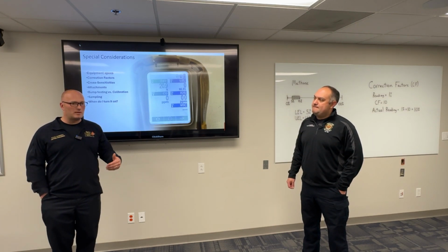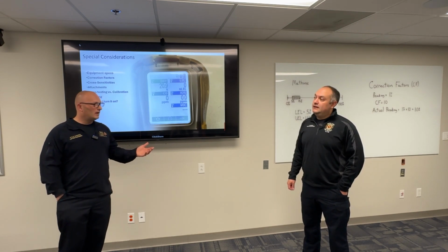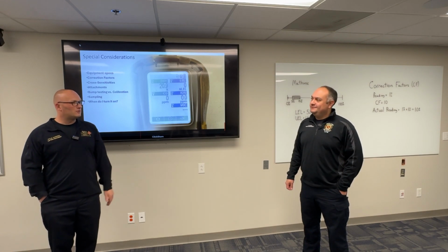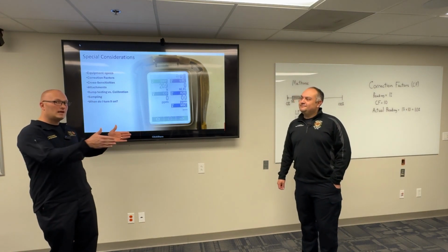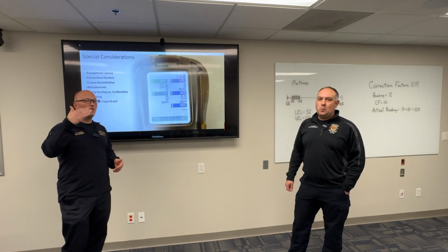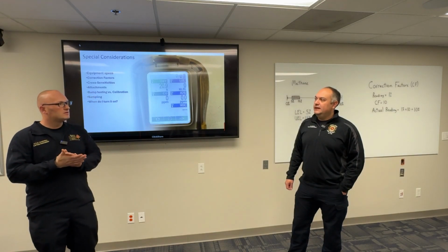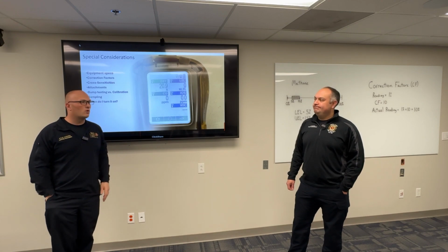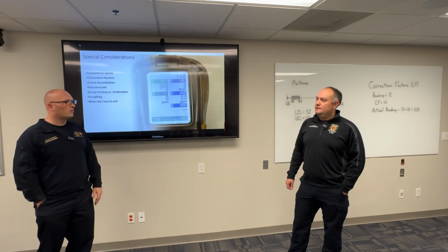I've had those calls where people have been baking all day long. It's around Christmas time, holidays right now. And 5 or 6 hours later is when their CO alarm's going off. And you try to figure out, well, I've been baking pies all day long. Okay, well, that's going to help me guide down to, hey, it might be something with your oven, and it's just taking that long for the CO detector in your house to reach that proper parts per million. So that's worth looking into whenever we dive into your CO calls, to help you trace down what you have going on.